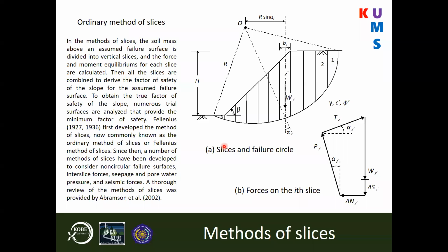It's not a perfect method because it does not consider the forces on each slice. It's one slice alone plus one slice alone. And then there are different ways of working with those slices. You can either, one, add all of them and divide by the number of slices to get an average. Or another method, which gives you the safest approach, will be to take the weakest link. Which one of all of the slices is the weakest slice?